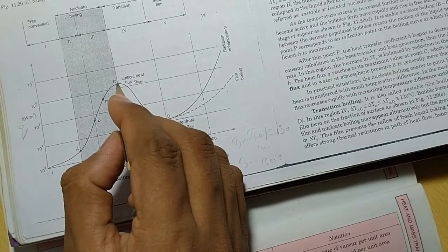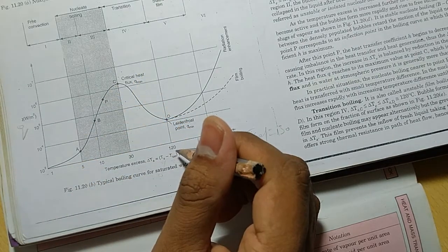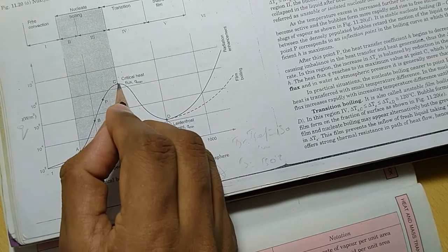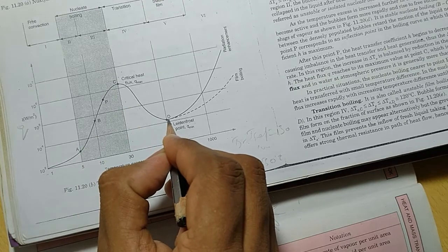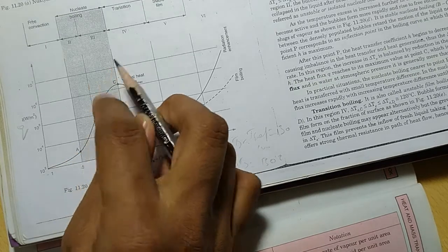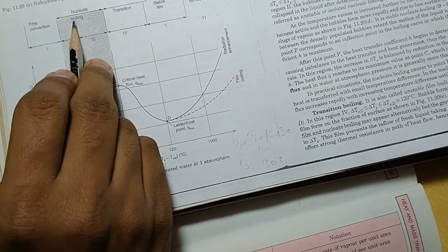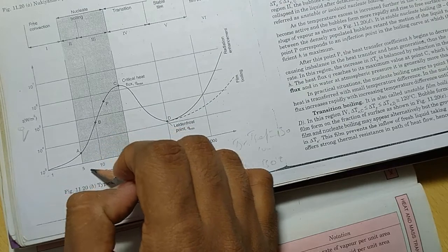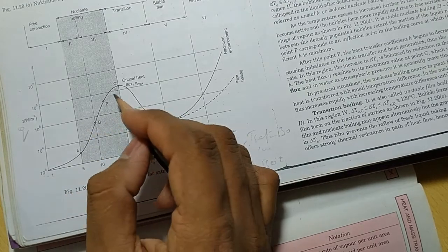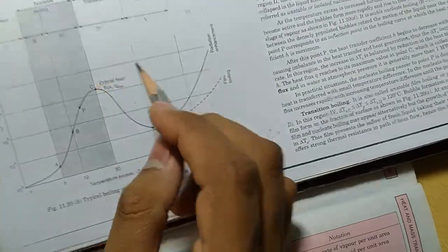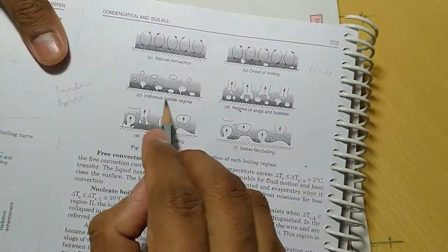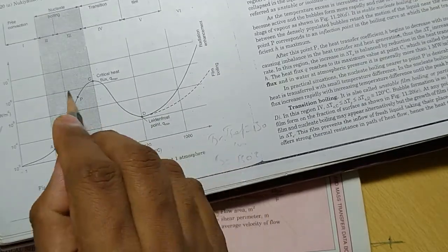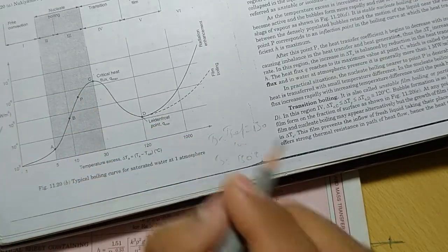This one you are going to call the critical heat flux. After this critical heat flux, when you keep supplying temperature, instead of increasing, the Q value goes on decreasing here. Try to understand. From this point to this point, you are going to call nucleate boiling. In nucleate boiling, first, some bubbles form. By going on increasing to a particular temperature, more bubbles form. After increasing the excess temperature further, instead of increasing, the heat flux goes on reducing.